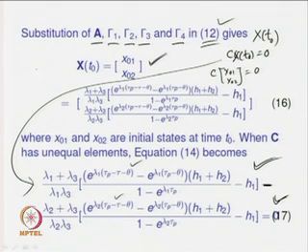C is obtained in such a way that in the expression for C, the first term has a positive value and the second term has a negative value. That way we have finally obtained the negative symbol over here. So, this first term minus second term has to give you 0, that has to be maintained to obtain sustained oscillatory output. Similarly, from the second condition, C x t 2 has to be equal to